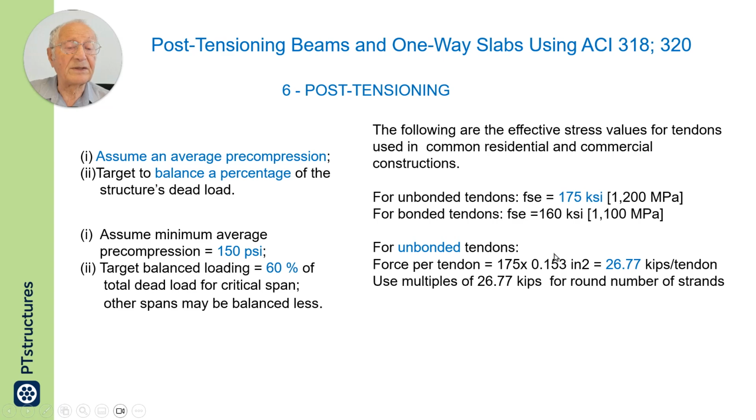So each strand has this cross section. Its final stress is this. So the force per strand will be 26.77 kips. I use this for the design.